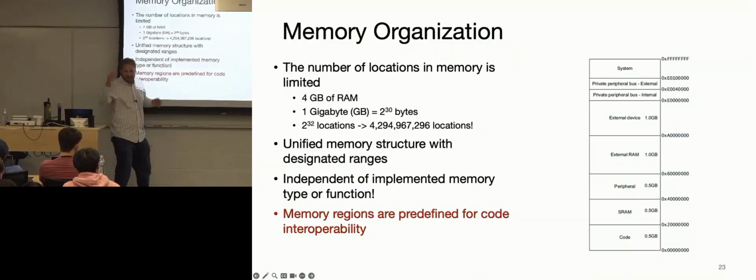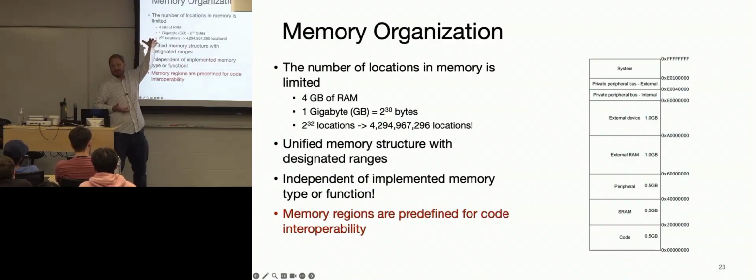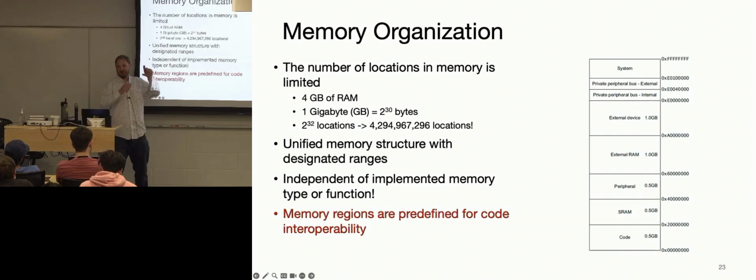So why don't they just have one entire reserved section? When you go to another processor that has more memory, you'd have to move everything else up, right? And now it's just more keeping track of all the little details, and my peripherals would start at different start and stop points. From a bookkeeping point of view, it's easier to say my timers always start at this memory address, regardless of how much SRAM I have below it. There's no reason you can't do it, it's just not convenient, and that's not how it's done.